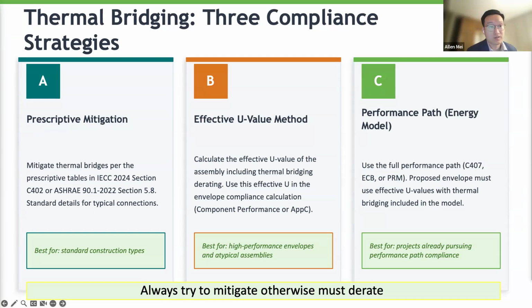We talk about the requirements. By the way, 90.1 has a little bit more than IECC. 90.1 has roof edge, and you also have to address any linear and point thermal bridging. They have a little equation in there. You just have to do the calculation and comply. They have an Appendix A where you can look at the numbers. Overall, 90.1 is slightly more stringent.